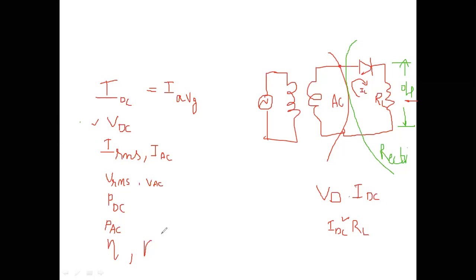So what is the rectifier circuit for? To convert AC into pulsating DC. If I get pulsating DC, then I will get a good amount of DC at the output. So rectifier ripple factor means how much AC component is present in the DC component. It is the main point to choose the circuit. This gives me information about which circuit you have to choose and which you should not choose.